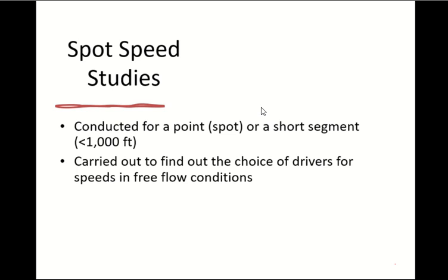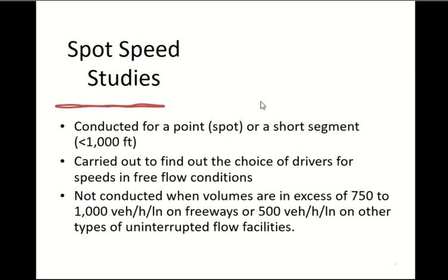Okay, clear? So yes, free flow conditions are ideal, but data collection in those conditions is basically not possible. So again, we have a range. If the flow goes up to these ranges, it's still considered free flow. What are these ranges? If it is 500 or less, no problem on any highway. If the flow is 500 per hour or less, no problem on any highway, street, whatever.